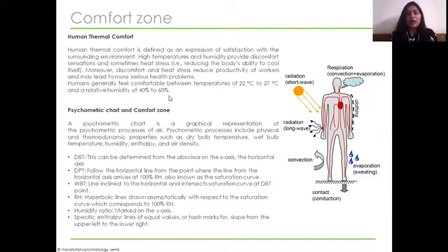Now let us see how graphically and technically we can chart and plot a comfort zone for human beings. The psychrometric chart gives you an exact and precise charting of the comfort zone in any climatic zone that you are studying. It is basically plotted against dry bulb temperature on the x-axis and wet bulb temperature on lines inclined to the horizontal along the saturation curve.